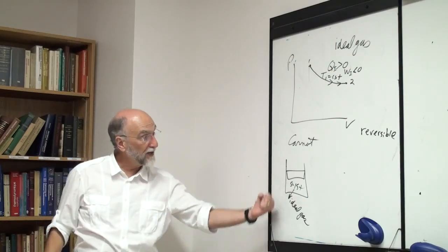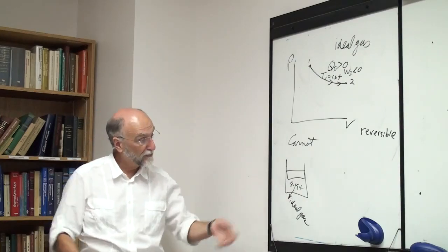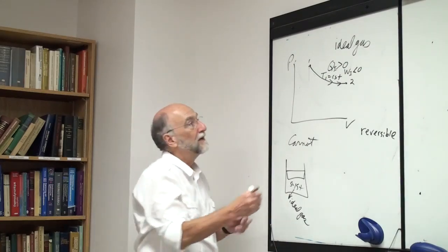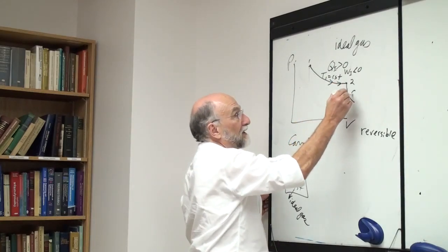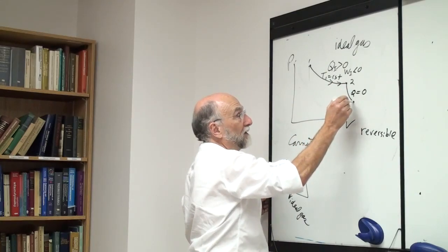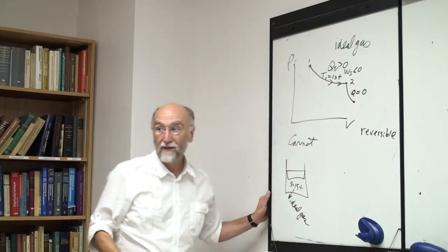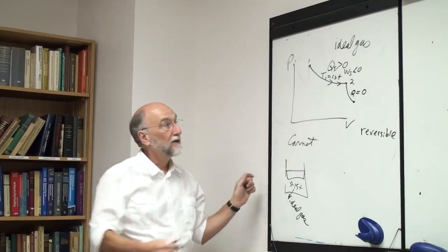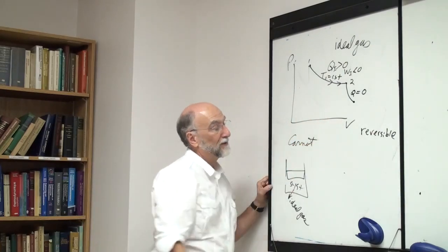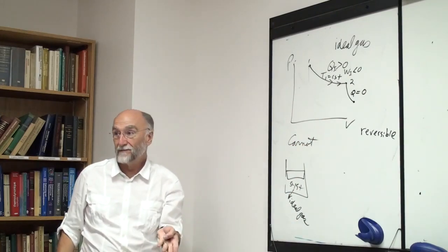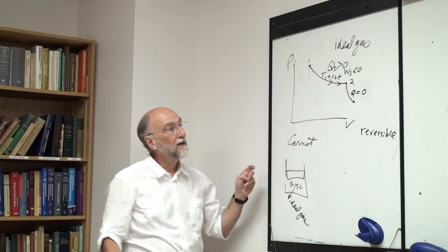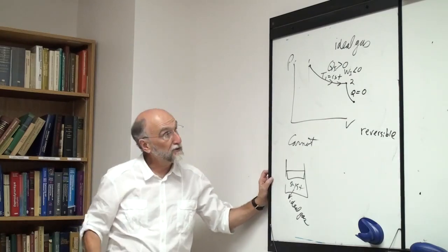So here you're heating the thing up. This is the high temperature step. You're burning your fuel, you're heating the system up, and it's expanding. This is the power stroke. Then we have an adiabatic, Q equals 0, an adiabatic expansion. So we consider the thing to expand a little bit more, but it's now insulated. So it does a bit more work, okay, but the temperature drops, because the internal energy is being used to do the work.